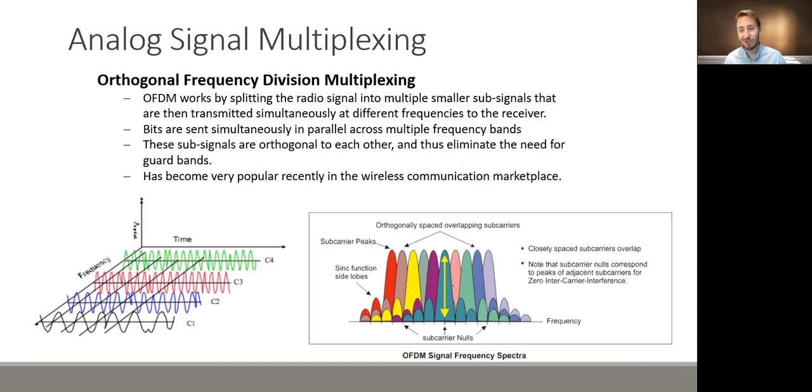The system works together really well that way. Everything is very pattern-like anyway. So you know what you're expecting on the demultiplexing side. You expect every frequency line to be exactly orthogonal to the other. And so there's less noise. And like I said, you can send your data in parallel through that frequency spectrum. And you're able to eliminate the need for the guard bands.